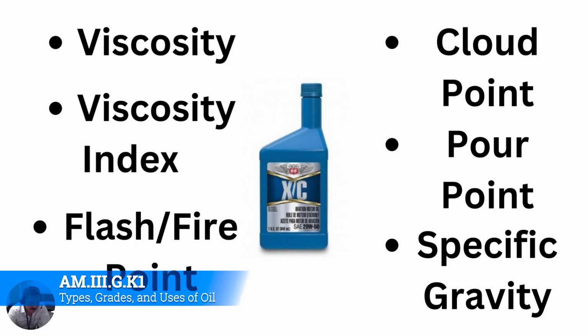But that being said, sometimes when you start digging into some of this engineering, you're going to need to know what specific gravity is, and all it is, it sounds fantastic, but it's really just a reference to water. Water becomes the baseline that everything is compared to. So if something is 1.1, that tells us it's heavier than water per gallon. If it's 0.9, it's lighter than water per gallon. So oil will float on top of water because it's lighter than water. Water sinks; it goes to the bottom. And so that's what specific gravity is.